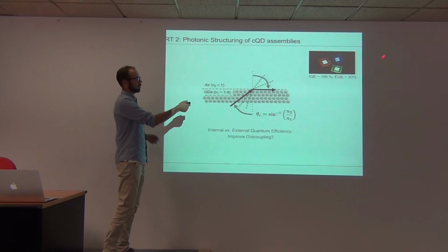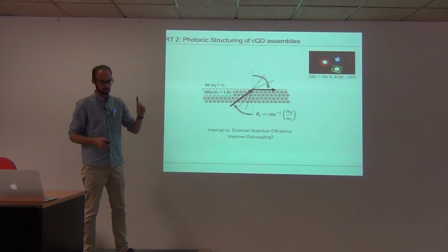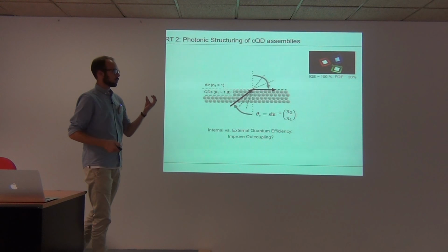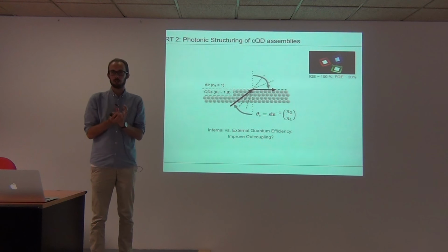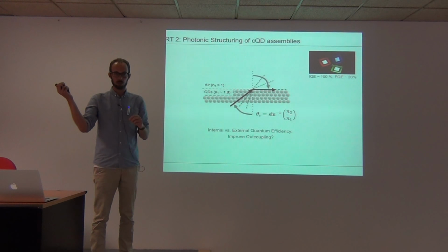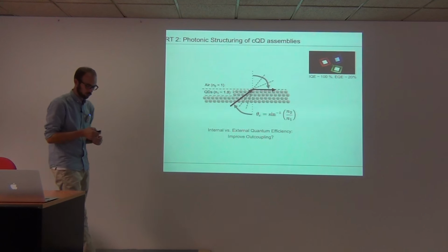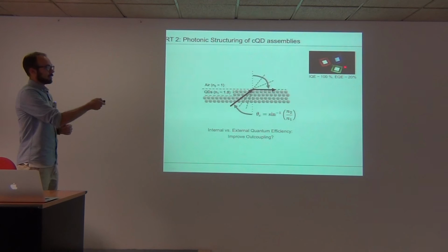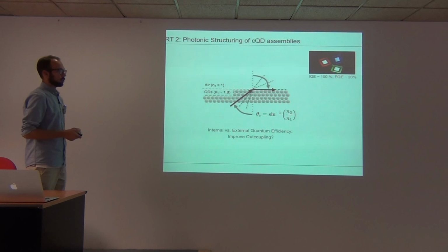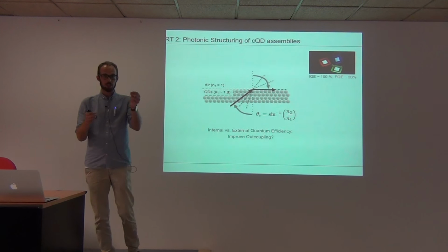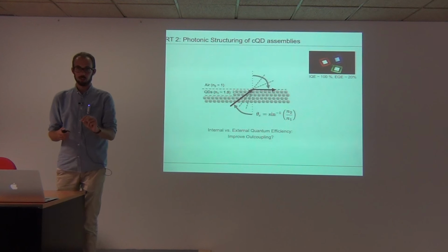So we have these TV screens, right? And people are also making LEDs out of these quantum dots. The interesting thing is that these quantum dots, thanks to all this passivation and everything, have quantum yields close to 1, meaning every photon that you use to excite them gives 1 photon out. This is really thanks to the advances in the synthesis. And actually these LEDs have internal quantum efficiencies close to 100%. That means that for every electron that you inject, you get a photon generated.